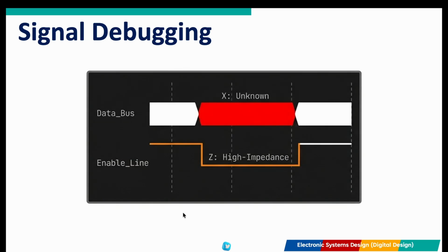When a simulation fails, systematic debugging in ModelSim is key. First, hunt for X values, which indicate unknown or uninitialized signals, and Z values, which point to floating or unconnected wires. To make verification scalable, industry practice dictates writing self-checking test benches that automatically flag output mismatches.